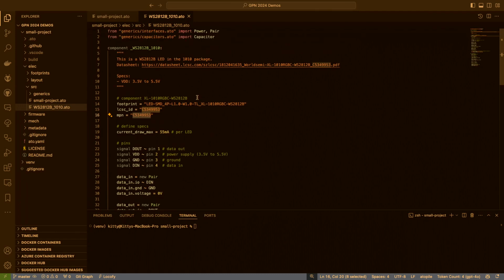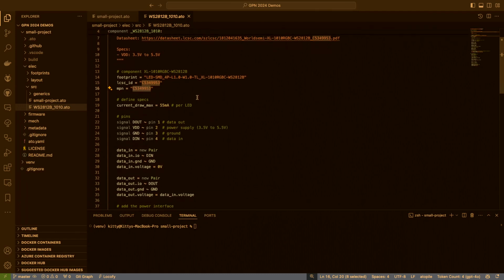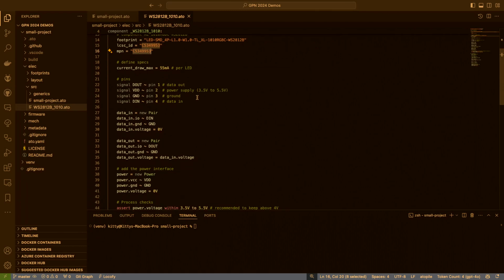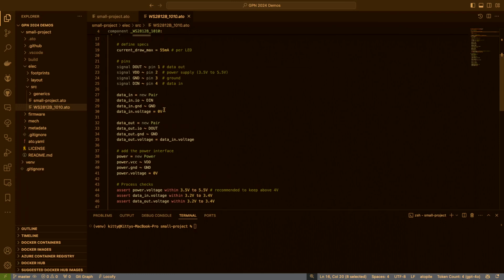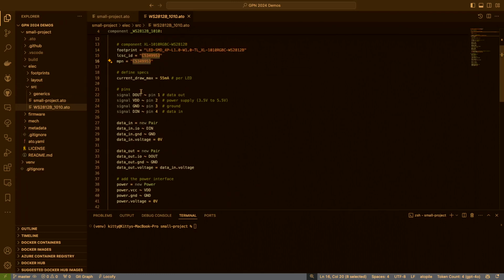What else? We can add comments at the top. There are a lot of interfaces that make the whole work a lot easier. For example, there's an interface component specifically for USB, for USB-C. The idea is that, for example, if you have a modern ESP32 microcontroller, which has pins for the data pins of a USB-C port, you can say what pins those are connected with.